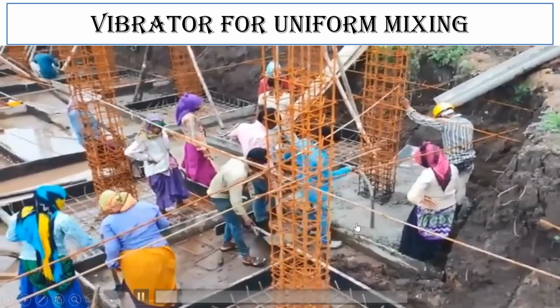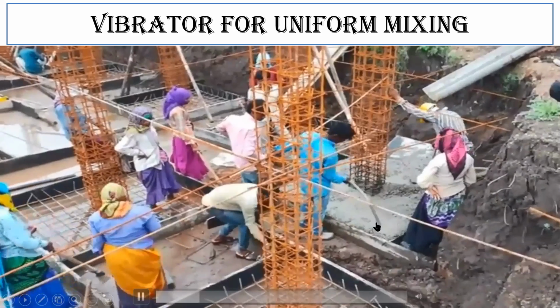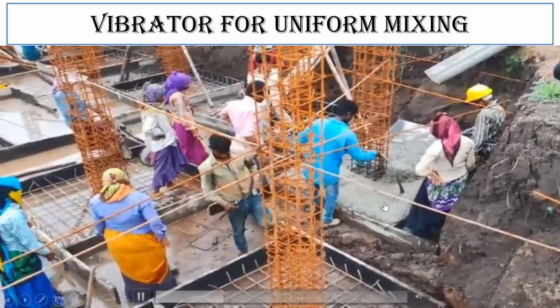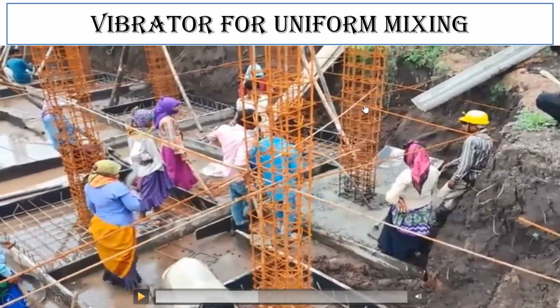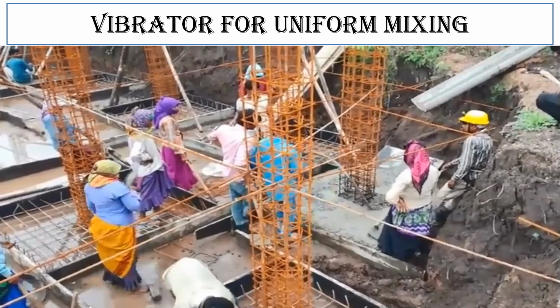So this guy is making use of the vibrator, and is trying to make the concrete flow easily, because you have a junction here, right? I'll pause it for a while. You have a junction of column reinforcement here. So the chances of your aggregate getting into this is very less. So with the help of the vibrator, we are trying to make this concrete flow in each and every part, so that the load distribution and everything will happen in a better way.